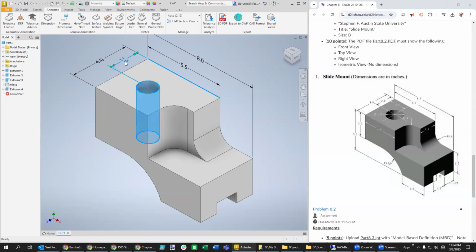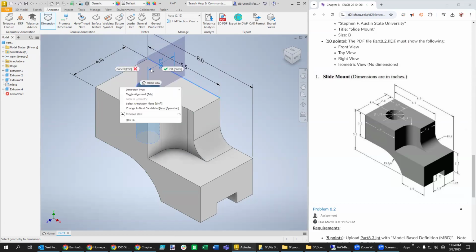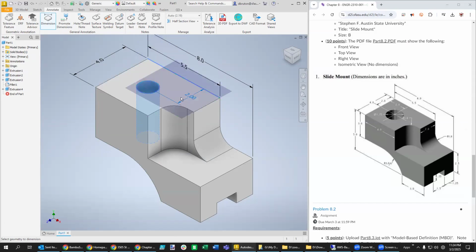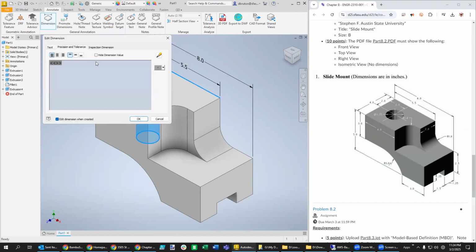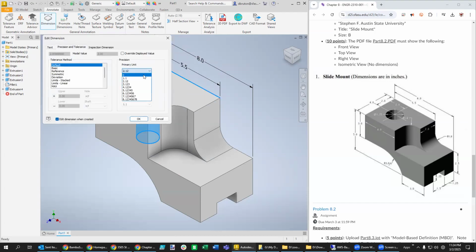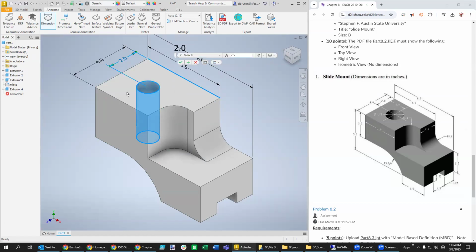So since the text is not aligned right, we're going to have to do it again. So I selected the wall thickness, or the walls rather, and then this edge. And then I right click on the gray area and say select this plane, pull out that direction, then hit tab to rotate the text. Place a number in place, then reduce the number of digits. Maybe I shouldn't make this a requirement, or I need to figure out how we can make a global setting so that it's doing that properly for us.